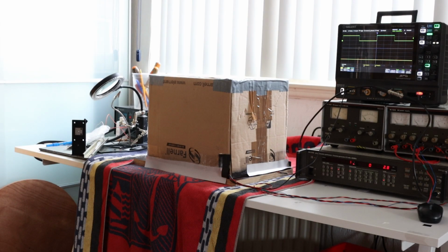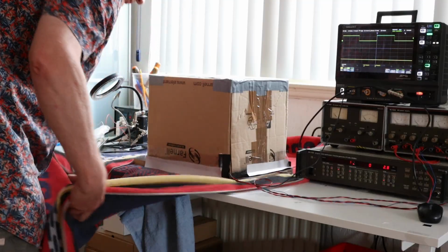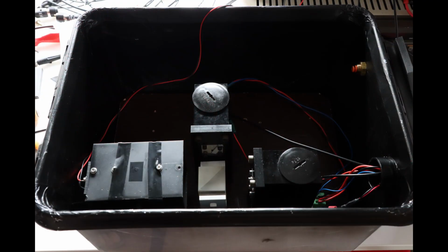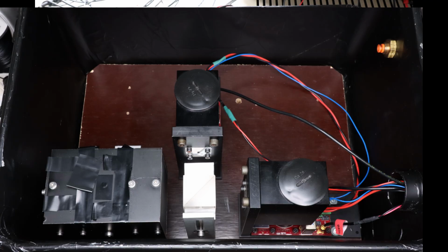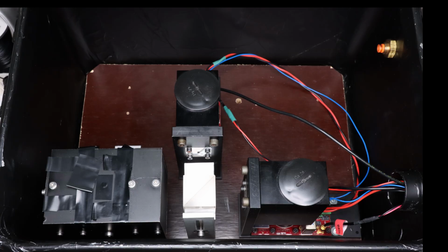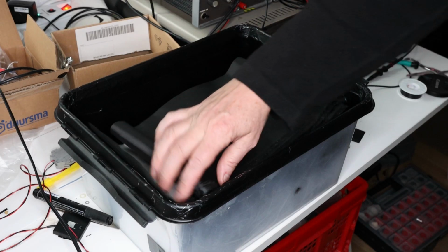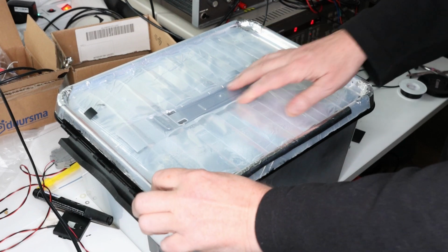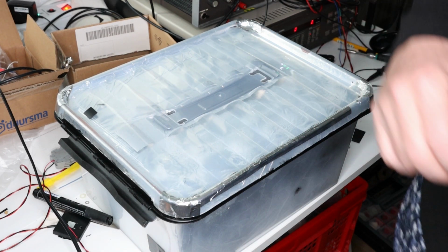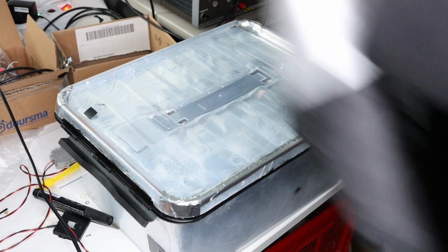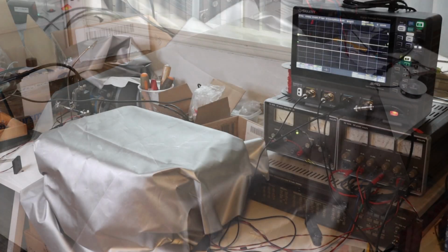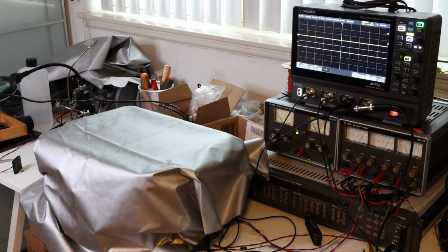As suggested by viewers of the photomultiplier video, I stopped using the cardboard box and the towels to shield the setup from external light. Instead, I used a plastic container that was completely light-proofed with aluminum foil, tape and black spray paint. The box, by the way, is small enough to be placed inside a freezer to reduce thermal noise in the detectors. For the current experiment, that wasn't really necessary because the thermal noise was always less than 5% of the signal, a value which I considered acceptable. So all measurements were done at room temperature to avoid all the complications of additional cooling.